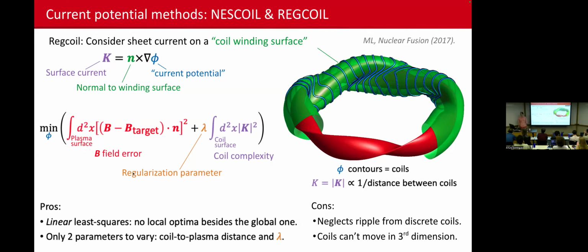Last follow-up. Okay. How do you discretize those voxels? Yeah, we basically just put little cubes. We take a big volume, discretize it into little cubes, and then we basically do splines to represent the current in each of those cubes. And then we have certain conditions that allow the current to flow. For instance, div J has to be 0. There are some constraints. I can send you the paper if you want, but there are some details there.